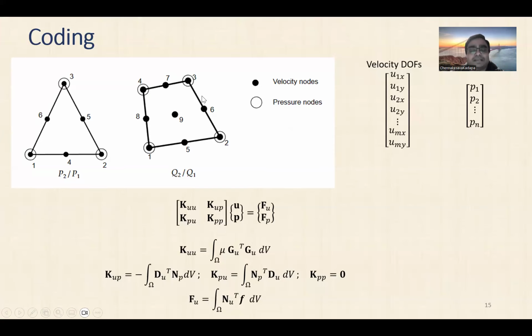That is also one of the reasons for using the standard mesh generator, so we get this mesh connectivity that we can use readily. Once we have all the element node connectivity, we already have the element node connectivity for velocity as well as for pressure. We simply extract the first 4. For triangular elements, we simply extract the first 3.